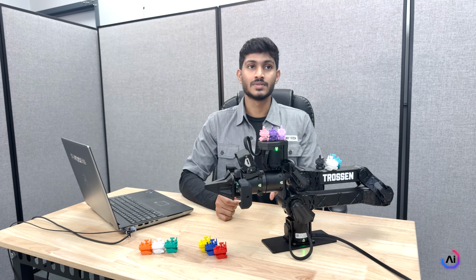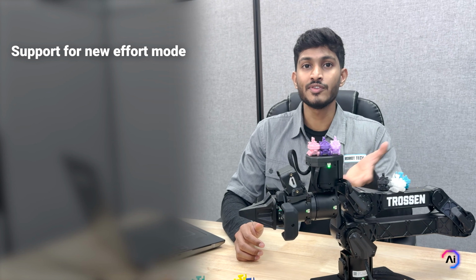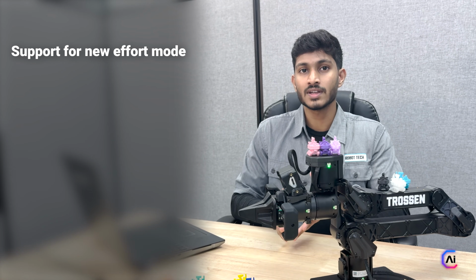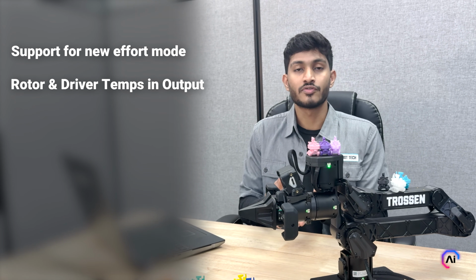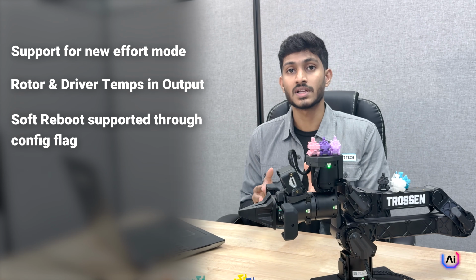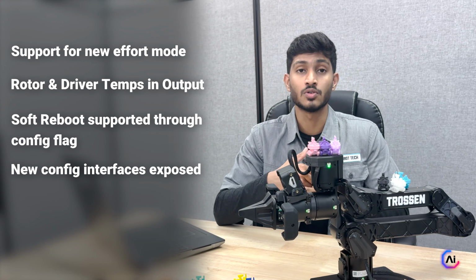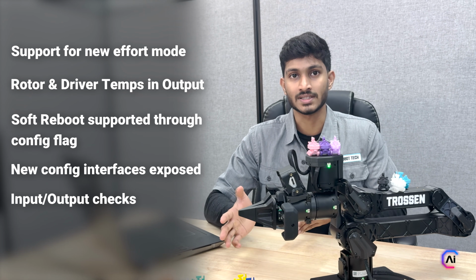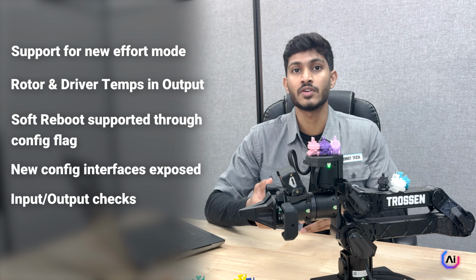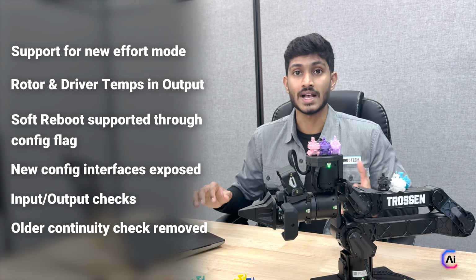To wrap things up, this update brings you several important things on both the controller and the driver side. Support for the new effort mode is fully integrated. You also get the rotor temperatures and the driver temperatures directly in the output. Soft reboot is now supported through a simple configuration file. New configuration interfaces are exposed, giving you more control over the joint limits and the motor parameters. We have also added input and output checks that allow you to catch things like infinite values or joint limits violations. The older continuity check has been removed.